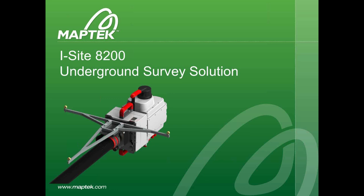The other option is to utilize our global registration, where you register the point clouds to each other and register the stope survey to the scan at the stope mouth. And then the scan at the stope mouth will be registered based on either known points on the wall being a prism, or you can use a total station to locate the tripod prior to setting up the scanner or afterwards, as long as the tripod hasn't moved.